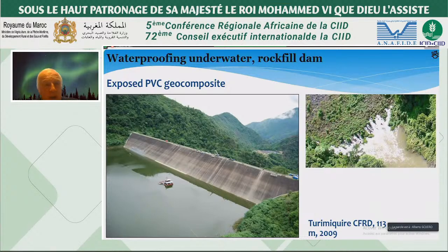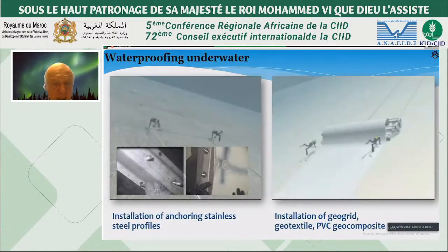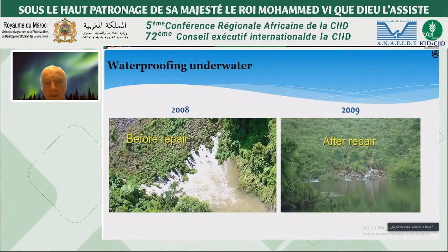Exposed PVC geomembrane has been used to repair rockfill dams underwater. We have a look here at Turimiquire concrete face rockfill dam in Venezuela. We can see the big amount of leakage before the works. The installation was totally performed underwater. We can see the installation of anchoring stainless steel profiles on the left and the installation of geogrid, geotextile, PVC geocomposite on the right. And the result is on the left before the repair and 1 year later after the repair has been completed.